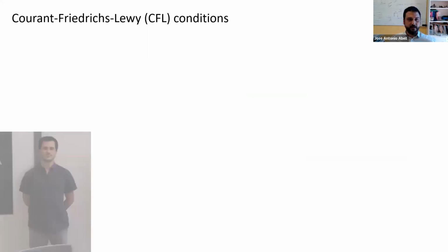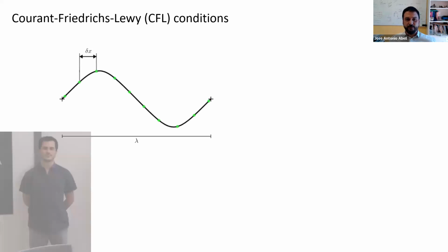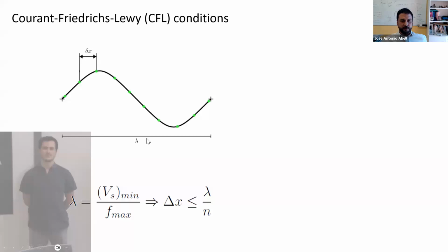The next thing you need to set up is, just a reminder, to make sure that you're doing wave propagation. There's no point in doing DRM if you're not going to be thinking about high performance or high fidelity tracking or resolving of the input wave field. So you need your shortest wavelength, which will be the shortest shear wave speed over the maximum frequency of interest, and the discretization needs to be such that you can resolve one wave.